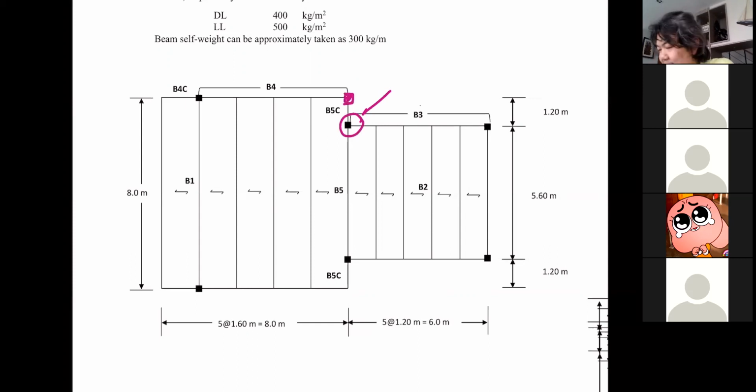I say this is perhaps more profitable because it reduces span length, and B3 can come into the column directly. And for B5, we have the cantilever portion out to support B4. It's better than having the columns at the pin location, where B5 becomes very long and has to support B3 before all the load goes to the column.